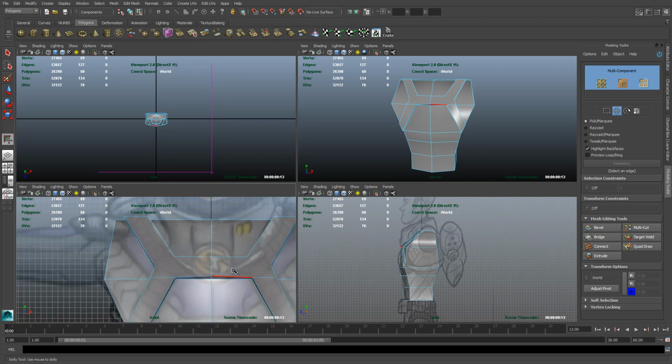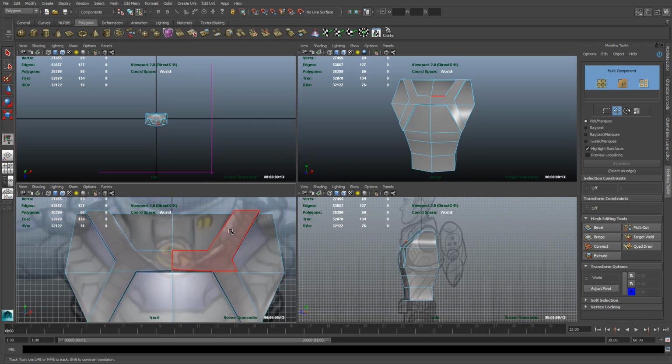But also, if you look, I've got this very irregular polygon here, so we need to definitely break this up into quads. Now, one way to do that, we'll just go to multi-cut and figure out how we can break this shape up into quads. And now I can see it, maybe you can see it too, but really all we need to do is a cut from here to here. We'll go ahead and hit enter, and then do a cut from here to here. And now, if we turn off multi-cut, we can see here we have 3 four-sided polygons.